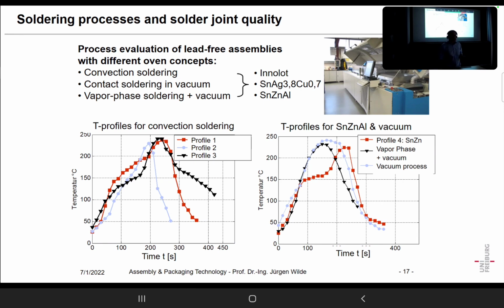And what you don't notice is that during condensation, the material on which the condensation occurs is heated up. For instance, you have a boiling pot and put a lid on that pot. The water will condense at the lid, and the lid immediately also will have 100 degrees centigrade.